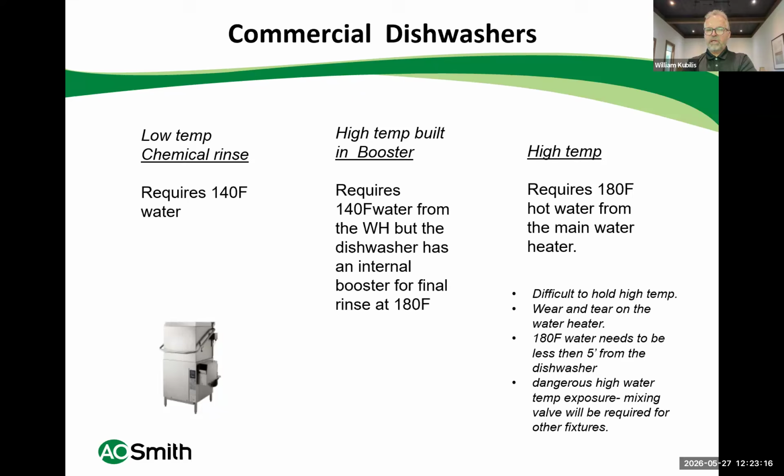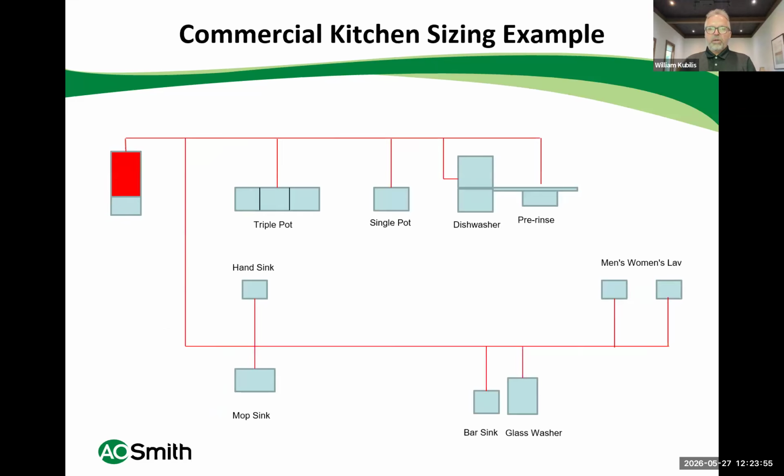You have a very expensive, big main water heater, and having 180-degree water in there is very hard on the tank. I don't think you'll get the best life expectancy out of your water heater by storing the entire content at 180 degrees. And then there's the challenge when you need 180-degree water within 5 feet of a dishwasher, so you're going to be circulating 180-degree water all the time. You will also need mixing valves, obviously, for the other fixtures. That's my note on that.